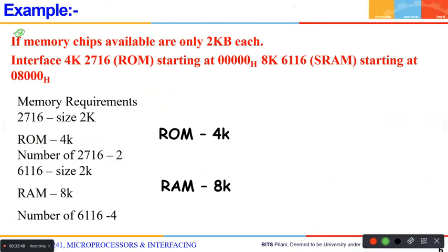Now, what exactly we're going to do here. This type of question you have already seen. What we need to do is design a memory interface to the 8086 microprocessor. How much do you have to interface? We have to interface 4K ROM and we need 8K RAM.